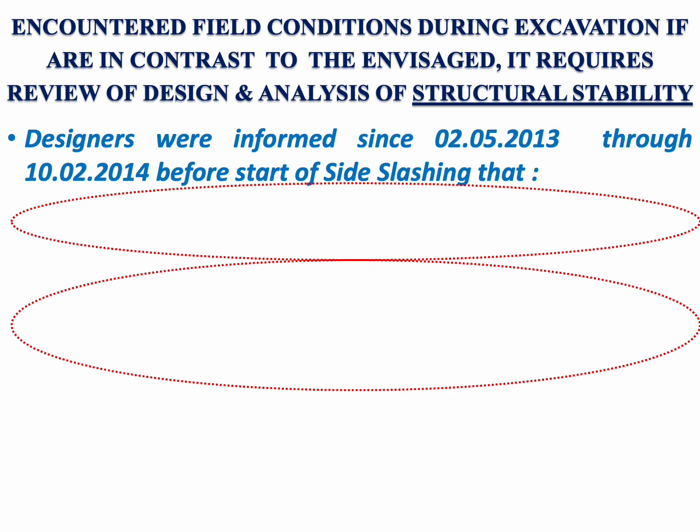Now, having the downstream surge gallery left unchanged for its layout and orientation, at least the structural stability needed to be ensured through a reviewed design, as was mentioned in the Hoek and Brown flow chart, which I discussed in the beginning: if the orientation and layout of a structure cannot safeguard it from the poised instability because of inclined geological structural features, then the structural stability has to be improved by providing properly designed rock support measures.